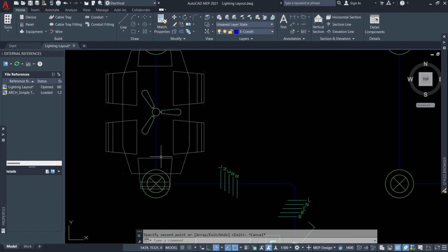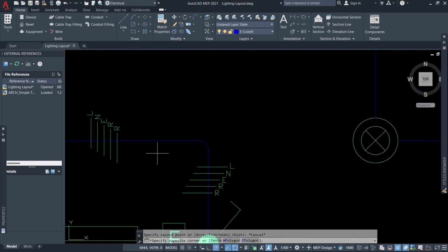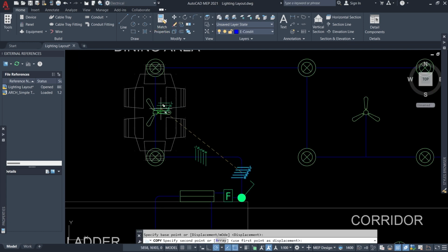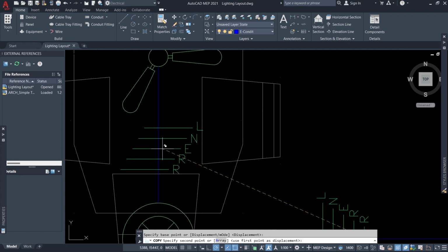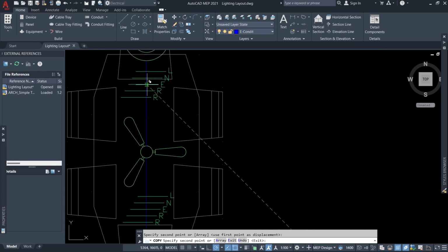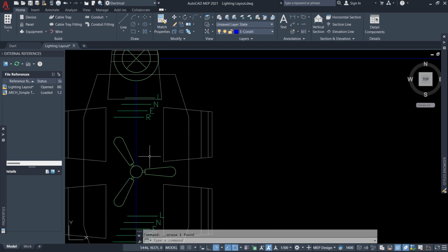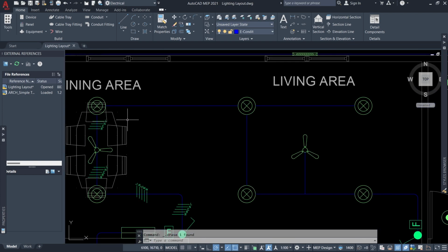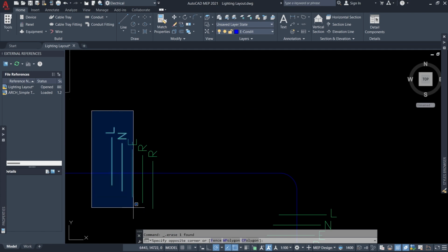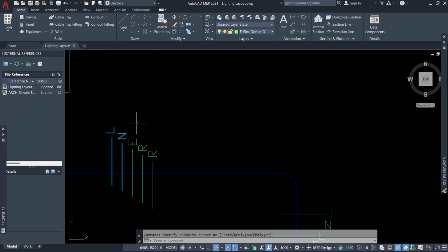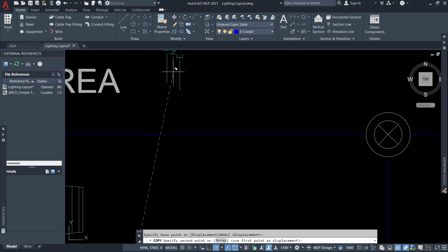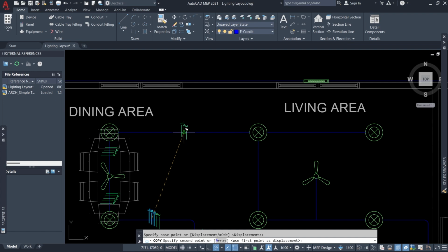After this light, we'll still have 2 return wires. Okay, sorry about that. We're still going to have 2 return wires over here, because still there's one going over here. But at this point, the return wire is going to be just 1, because after the fan, only 1 return is going. And then at this point, there is no return wire. The only thing going there is the live, neutral, and earth. Okay. It's always important to understand that.